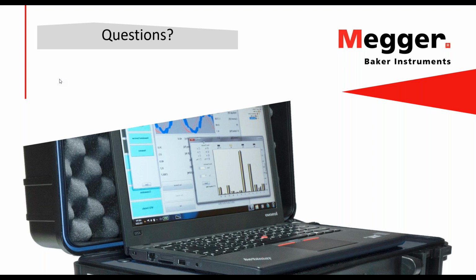However, the most damaging effect of voltage unbalance is the fact that it will create current unbalances in the rotor that are way higher in terms of the percentage of unbalance than the percentage of unbalance of the voltage in the stator. What that means is that you will have a magnified effect on the current in the rotor, which is very damaging for the machine.